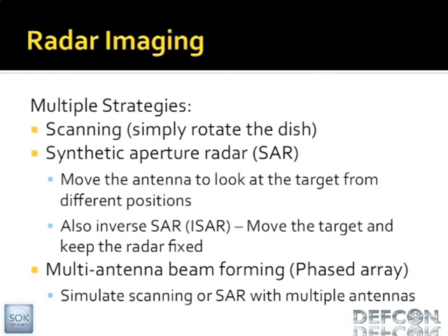There's something called synthetic aperture radar, which basically means you can get better resolution if you have a bigger dish. But the problem is that bigger dishes are more directional. So with synthetic aperture radar, you're taking coherent measurements of the signal at different places, and you're trying to simulate having a larger dish. The reason is so that you can get a finer resolution of space. If you just point it in one direction, I think the beam widths on these things are 40 degrees or something, so you couldn't see anything out there.